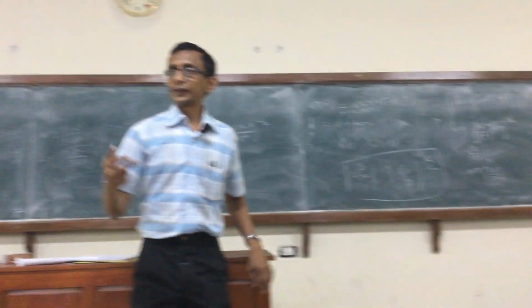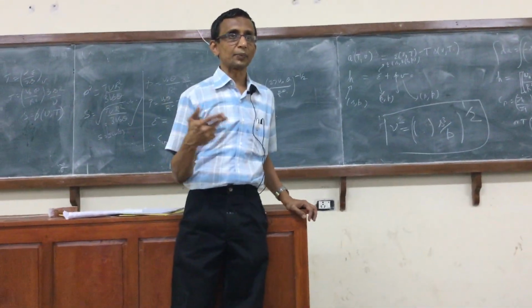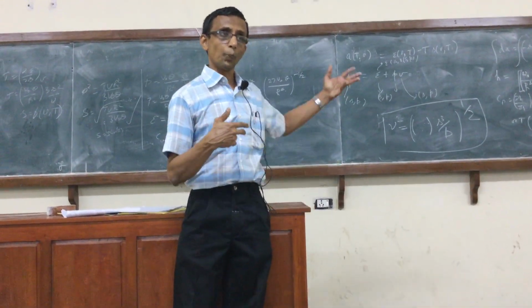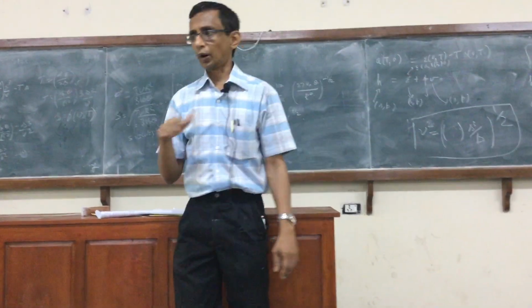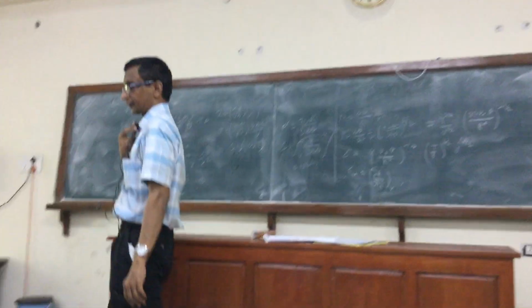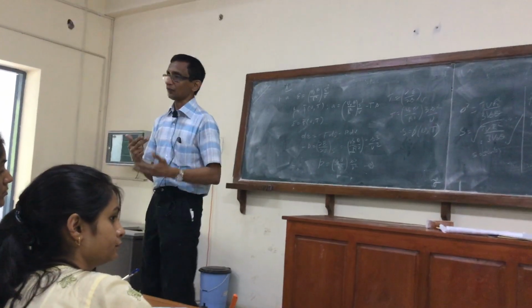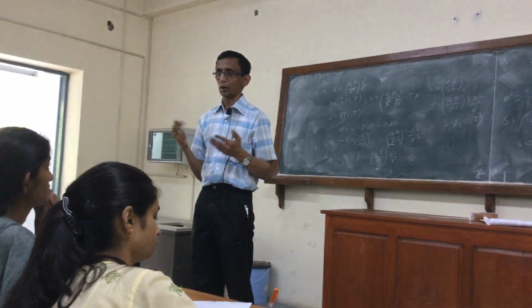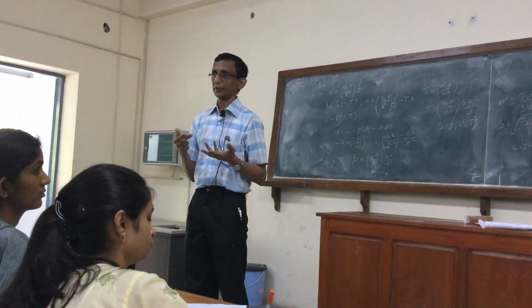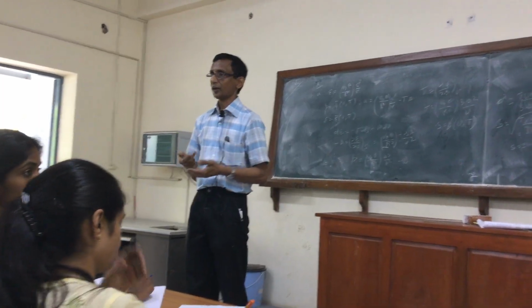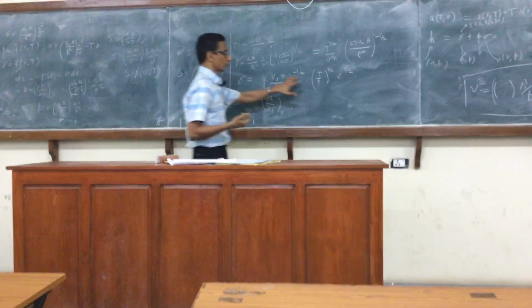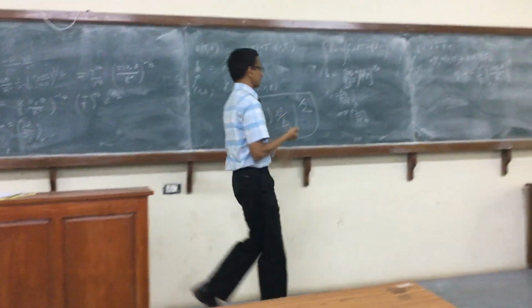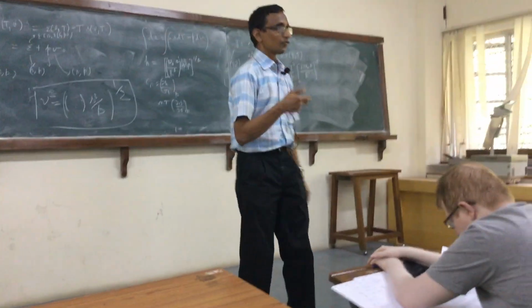Either you express H in terms of T and P or S in terms of T and P. You can do both and verify whether your answer is correct. So you can get all properties, and the whole idea of this exercise is to show that from the fundamental equation you can get all possible properties. The equation of state, E expressed as a function of V, is very typically what is required, and also the specific heats and various other fundamental equations.